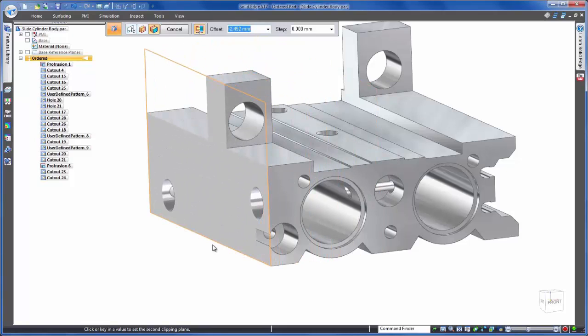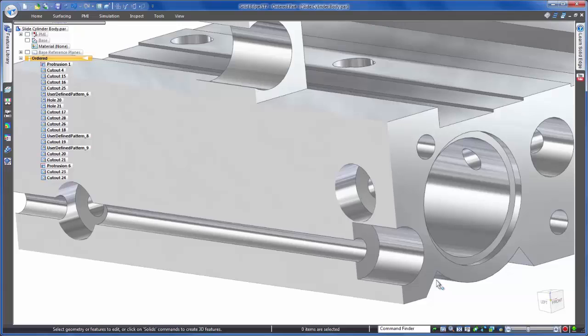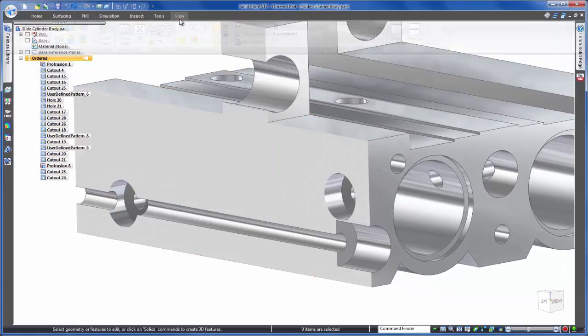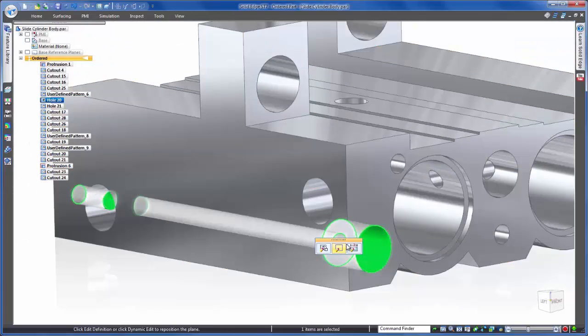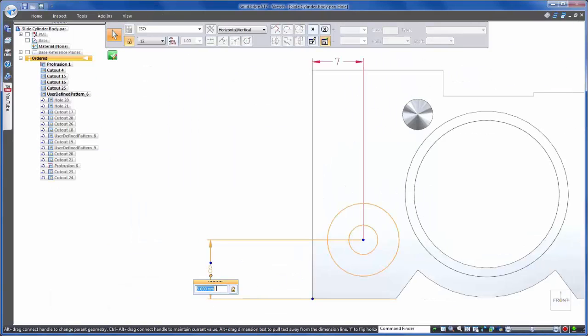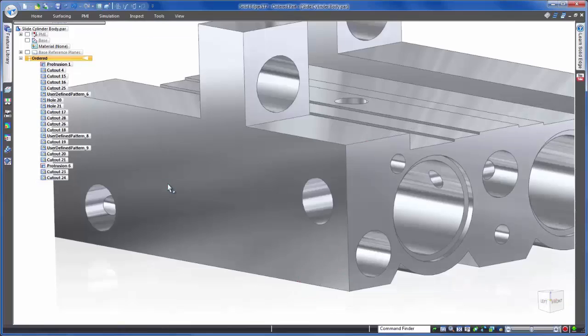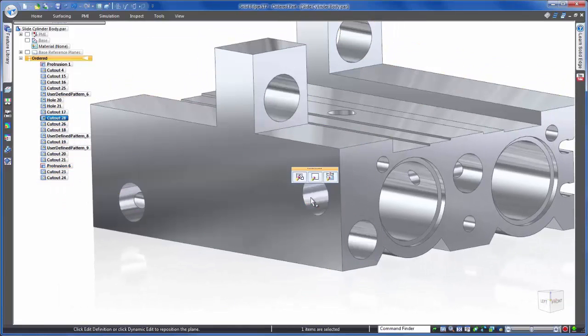section view through the holes needing editing. This is a great tool for parts with complex internal geometry. Using the dynamic clipping plane option allows a section to be shown in any particular location on the part, as well as the geometry located within. Now that we can see where the blow-through is occurring, let's edit this front hole. Once again, by editing our profile, we can either key in exact values for dimensions or let Solid Edge do the calculation for us.